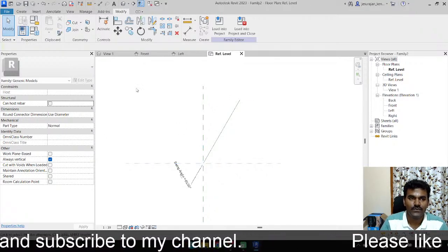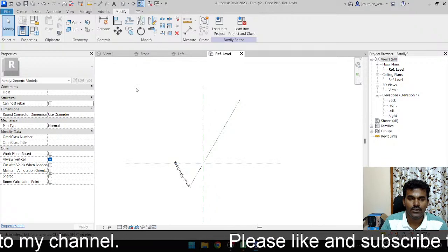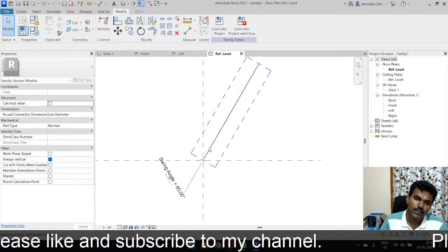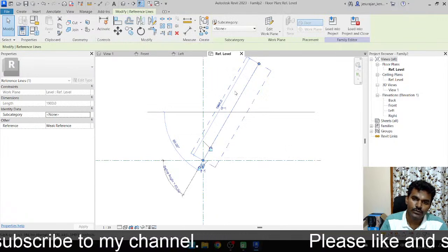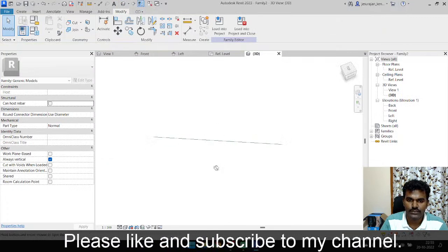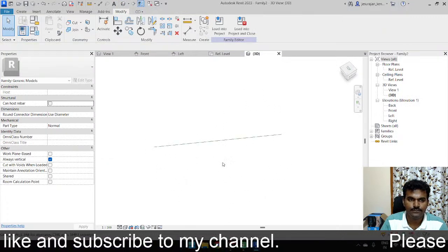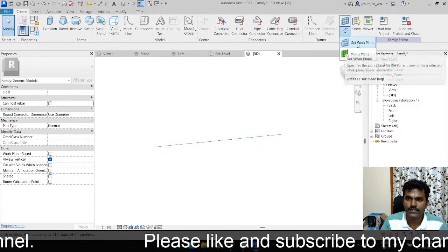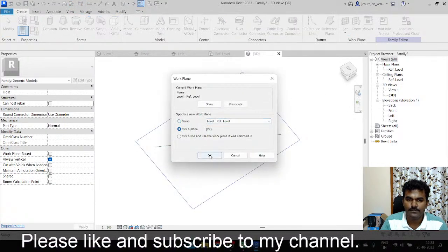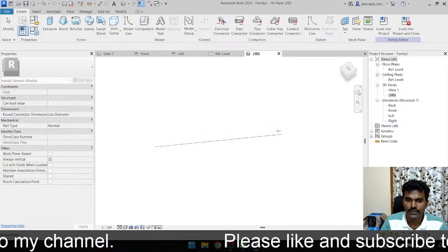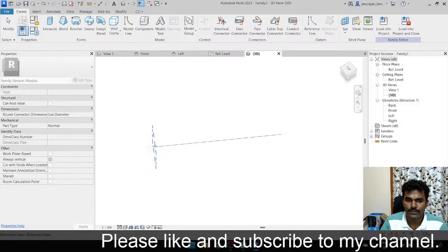Okay, now what can we do? We have the line. Let's go to 3D. This is the line. Go to create and set a work plane. Set work plane, pick a plane, and you can see this reference line will give you 4 reference planes.